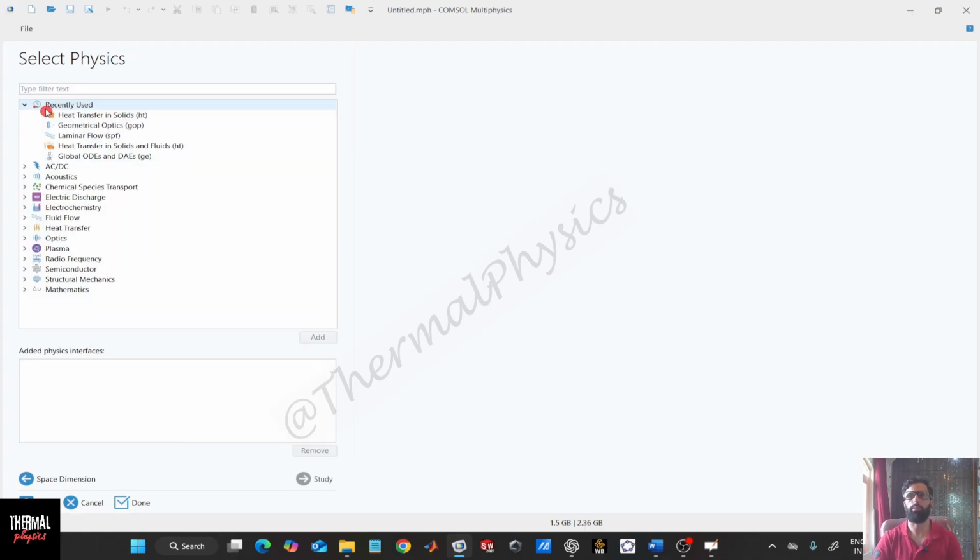Now there is one problem in choosing 3D, 2D or 1D, which is that we can have temperature gradients unless our Biot number is much lesser than 0.1, and the Biot number depends on thermal conductivity. For our problem thermal conductivity is not given, and that's not even required. Thermal conductivity for lumped capacitance models is only required to check whether the model is valid or not. So if we keep any value of k, it doesn't matter. The result for the lumped capacitance model will not change by putting any value of k.